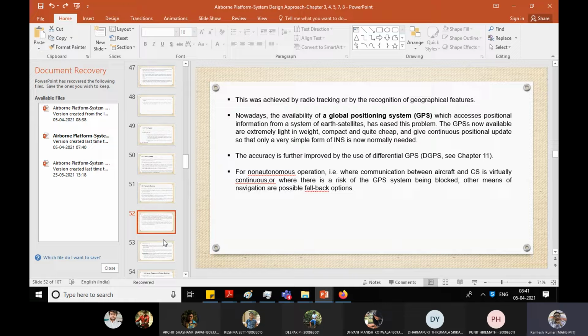So you can convert the geodetic system to the Cartesian, and that information you can pass further to the inertial navigation system for the calibrations. Okay, because of the GPS receiver availability on the aircraft, now you can go ahead with the cheapest type of inertial navigation system as well. Because this does not require any external source from the ground. Because the GPS receiver is already on board, that can take care.